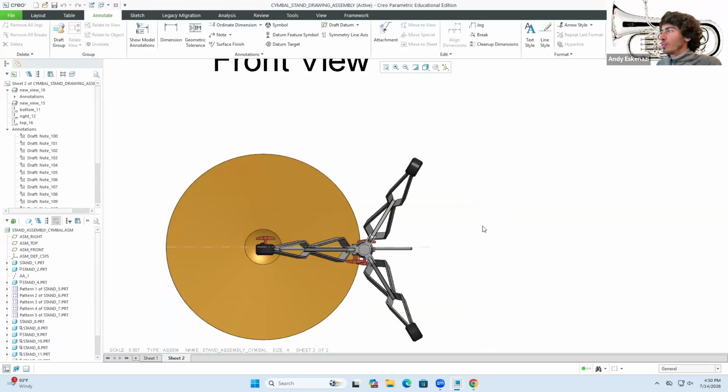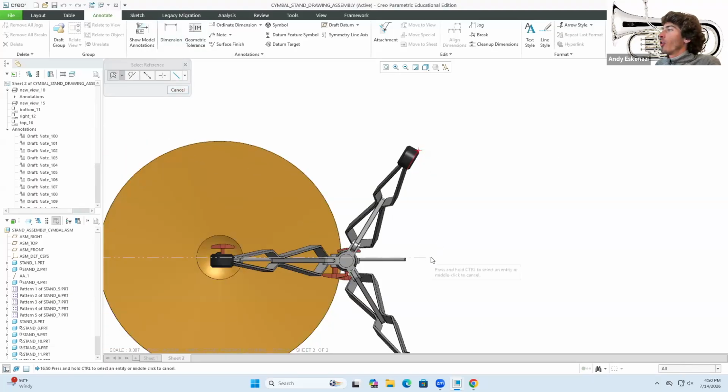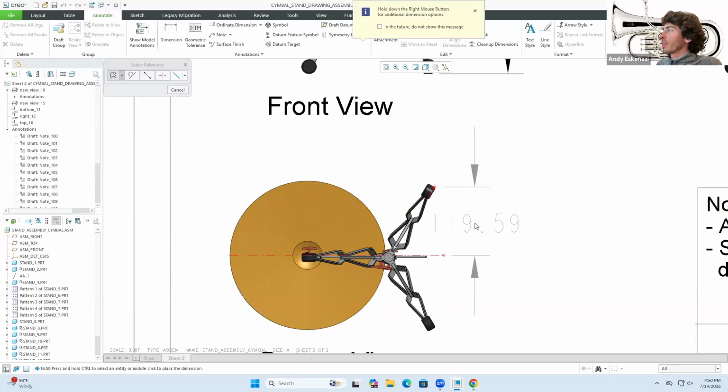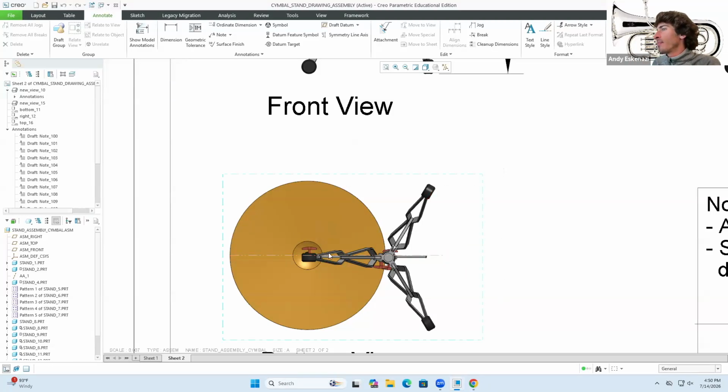If I wanted to do this properly, I would go back to dimension, click on that point, and then click on another point or hit control on that line in question. And it's going to display the correct property because it's now with respect to the particular object itself, the one that was scaled in the first place. So you can have it as 119.